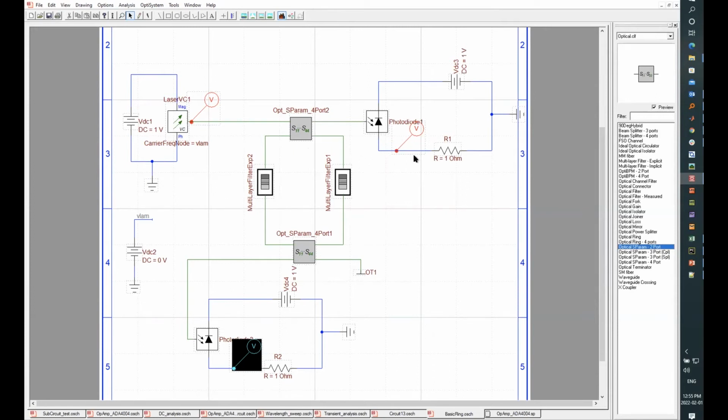Now, also we have hooked up the OptiSPICE standalone software with MATLAB as well. So what happens is, instead of using these normal probes, we can use the probe MATLAB, which will open your results in MATLAB. And also there is a way to run any MATLAB script. Let's say if a user has to do some post-processing of simulation results in MATLAB, there's a way to define a path. There's a code in JavaScript wherein you define the path, and then once you double click on the probe, it will automatically show you the results in MATLAB, as well as it will run your script for any post-processing analysis.